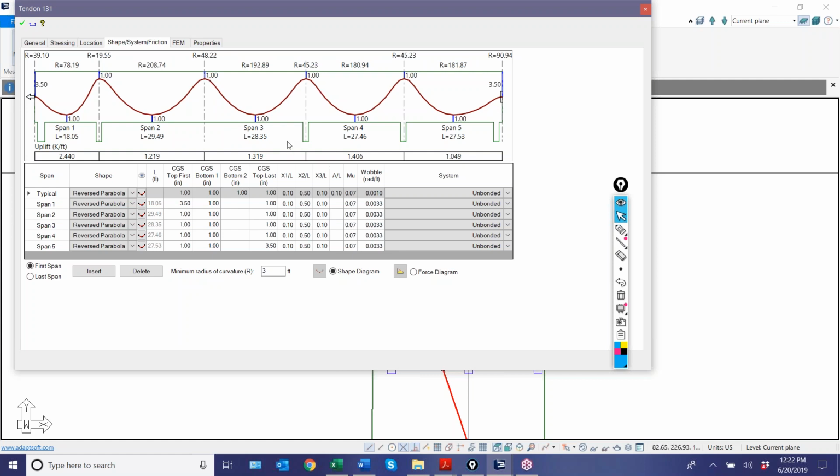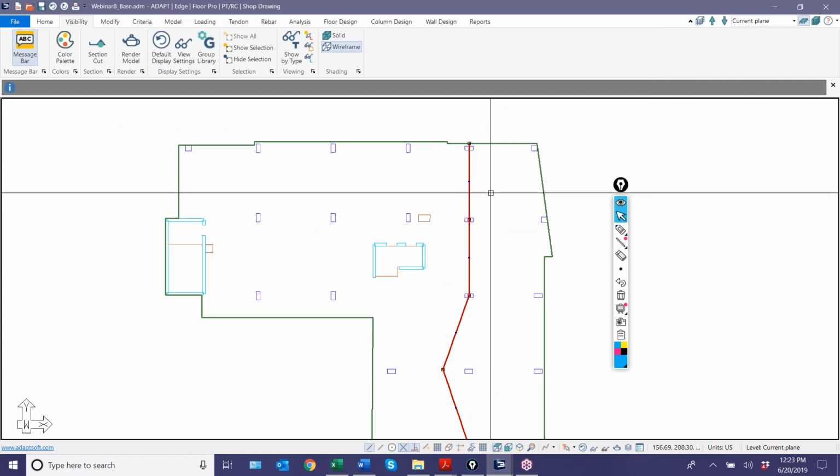This can be calculated without need of finite elements. You can just calculate it based on the geometry and the force. And we use this number when we calculate the uplift for the simplified method. So if there's 12 strands and there's 3 of these bundles, there's a total of 3 times, let's say 1.32, and we use that as the uplift and compare it to the dead load, the sum of the dead load applied in the span, and we use that to produce the balance loading. That's different than the balance loading check using finite elements.